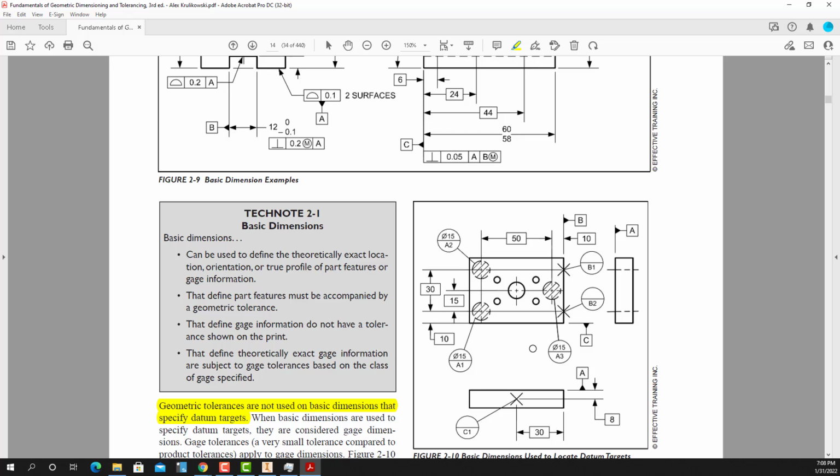We have 3 flathead pins. They're hatched and have a phantom line on the outside. This is datum A1, A2, and A3. This is the diameter of the pin. It's flat because I see a circular flat face.